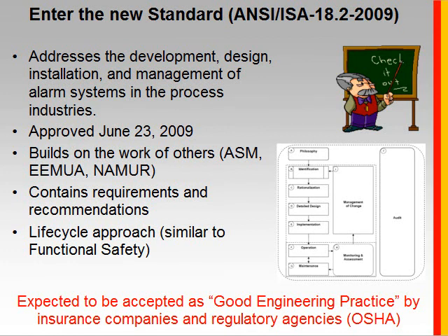If you're familiar with the functional safety standards, ISA 84 and IEC 61511, you'll notice a similarity in the approach, and that is, in alarm management, we take a life cycle approach. It's a continuous activity. It's not a once and done activity. It requires continuous attention. So just like functional safety, we take a life cycle approach in the design of the standard. Now, also similar to functional safety, it's expected to be accepted as good engineering practice by insurance companies and regulatory agencies such as OSHA.